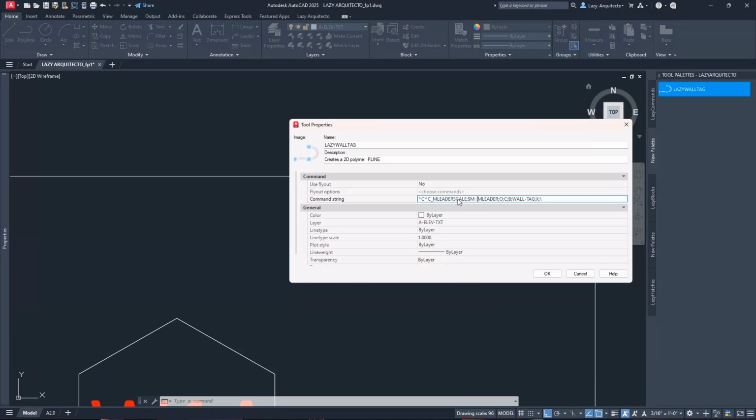A DIESEL expression is a more advanced way to utilize macros in AutoCAD. And for this portion, oops, I forgot the other dollar symbol. But what we want this DIESEL expression to do is, in parentheses, we want to get a variable. What variable we want? We want this system variable called DIMSCALE.